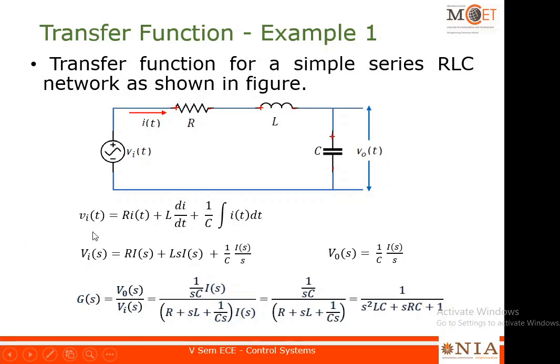So now after writing the differential equation, please take Laplace transformation on it. When you take Laplace transformation on this differential equation, V of t will become capital V of S. Because in time domain the variables are written using a small letter, and in a frequency domain the same letter will be in capital, and the variable will change from t to S. In time domain the variable is t and in Laplace domain it is S.